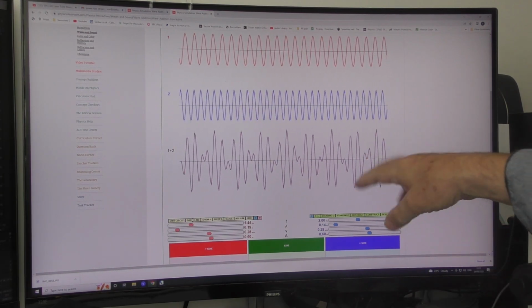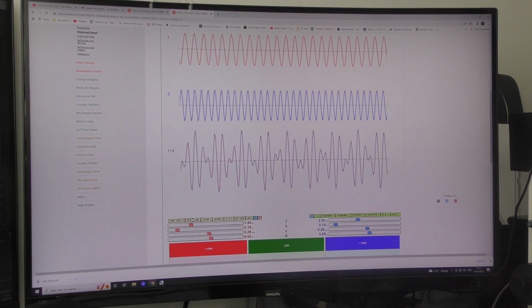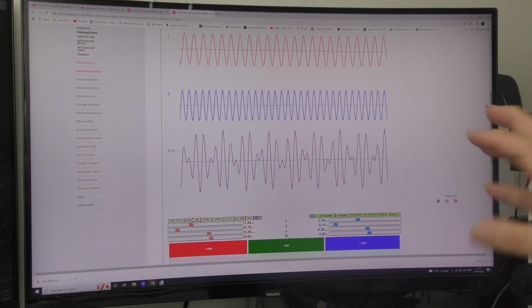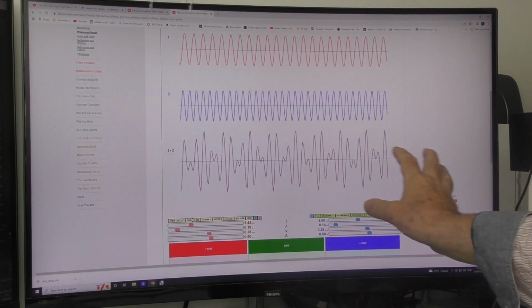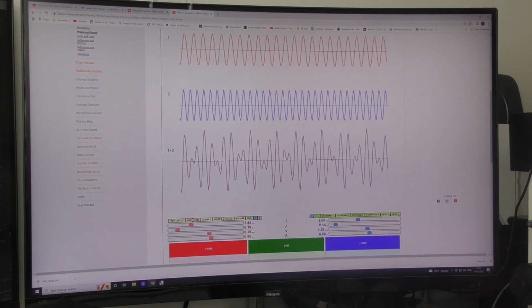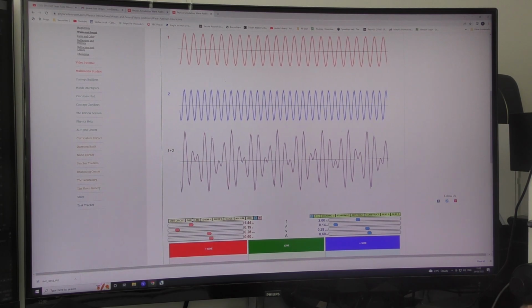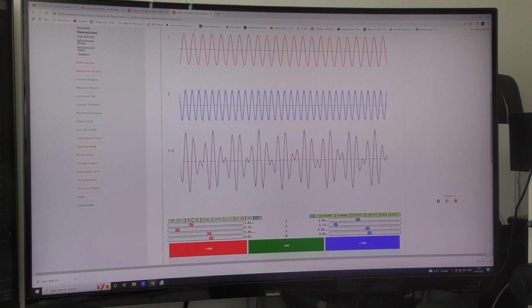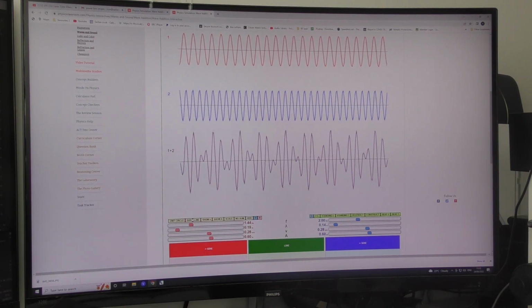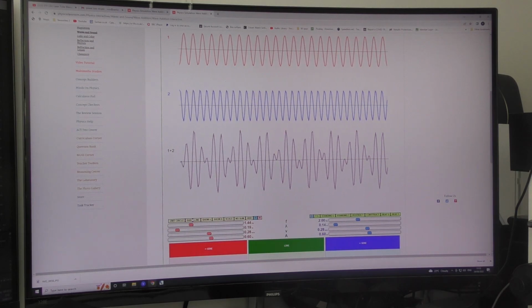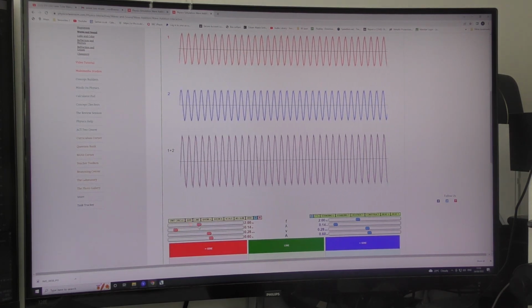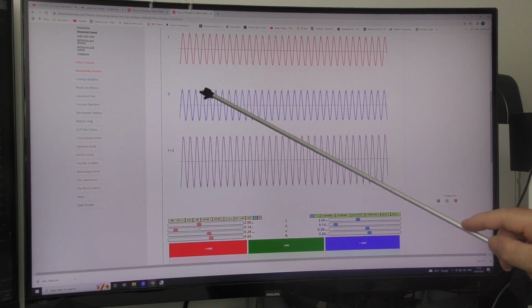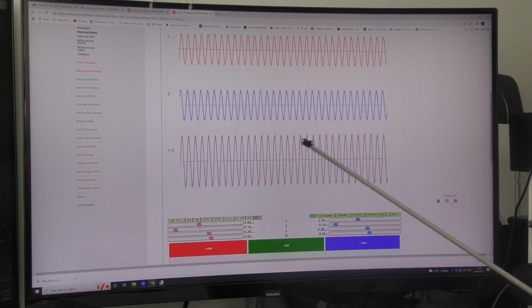like that, the error is so rapid that you might not even notice the problem, because the error is built in between lots and lots of pixels, and you wouldn't notice that some of those pixels were slightly smaller than the others. There would be an overall pattern change, maybe in the lightness or the darkness of the picture, but you wouldn't notice that pattern unless you were doing some very simple plain engraving where there's no supposed change to the background. You would then see that pattern in the background, as I demonstrated to you on some of my previous videos. So I found that I only had to change my pulse rate by 1 Hertz in 10,000 to get them to match and produce a nice error-free burning pattern.